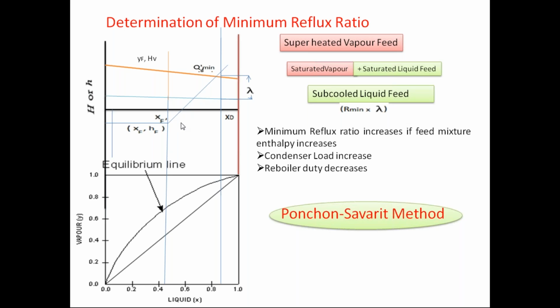So first you draw this line, then you can see one point here which is falling on the equilibrium curve. Again you can see this, and then yeah. This line, the pinch line which you are drawing, should be adjusted such that these points, when you bring them down to this line and this line, both intersect on the equilibrium line.